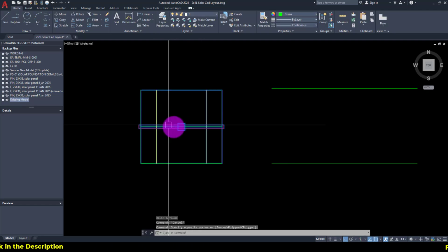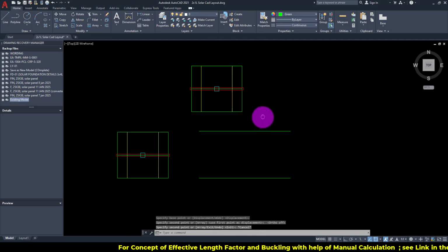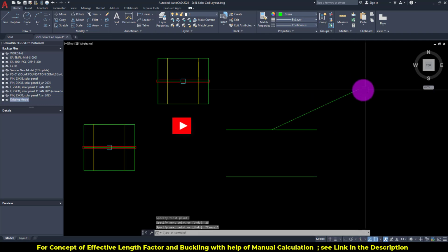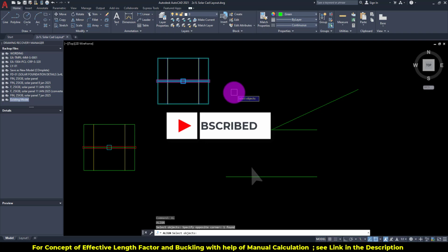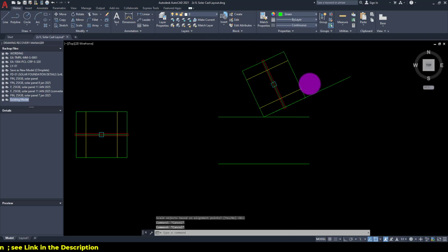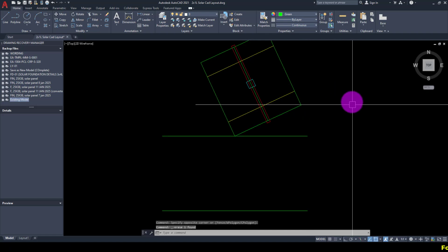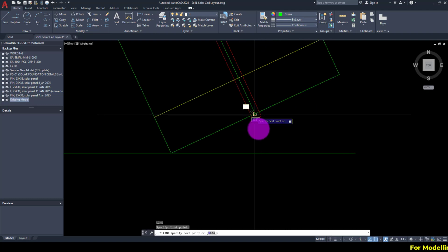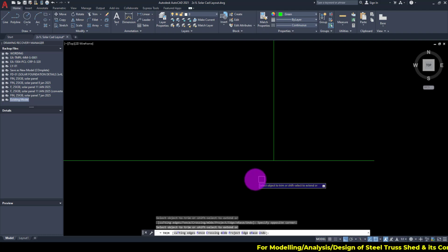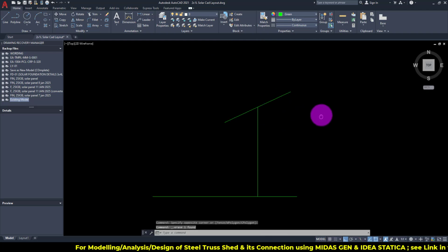Let's just copy this and paste this. Now make a line of whatever length but inclined at 25 degrees. Align this structure array with this line towards the smaller dimension as we have discussed. From this center to this one, this is the column, and create the line here to here and remove this array.